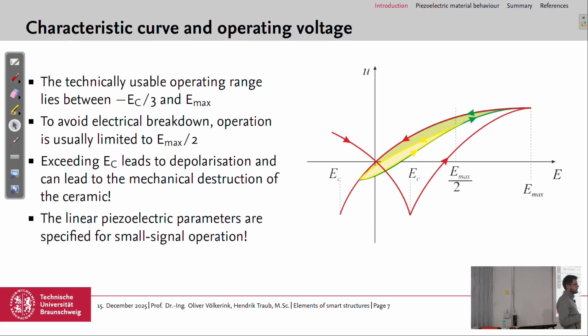How can we calculate it? I'm not sure if we can really calculate it, but it's always specified for the material, so you know it from the data sheet of the material. And you also see it if you do the experiment. If you increase the field above Emax, you would get a straight line. So the displacement or the strain would not increase anymore. So if you increase the field and the strain or the displacement does not increase anymore, then you have reached Emax.